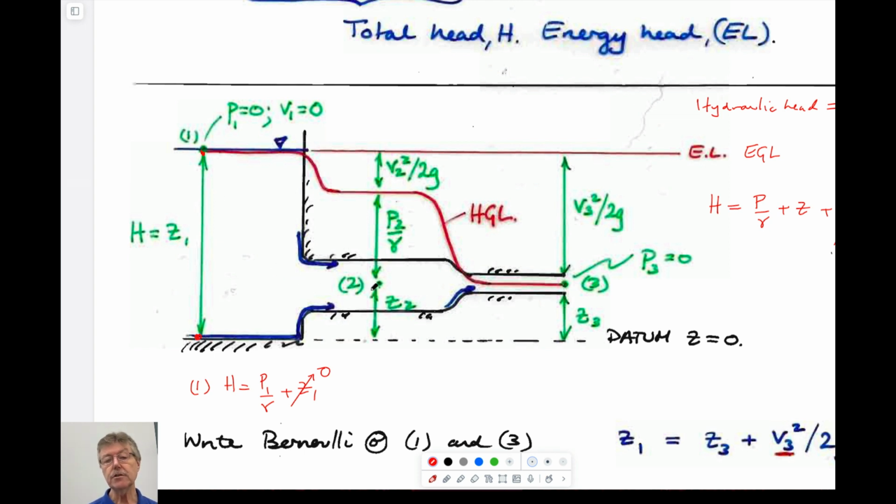As it comes out of this nozzle, now all of a sudden it has a velocity. So the velocity at this point is non-zero, so you have some amount. The elevation of this point is non-zero because you know that. So these are the two things that you know: non-zero velocity and non-zero elevation. And so the difference between those must be the pressure.